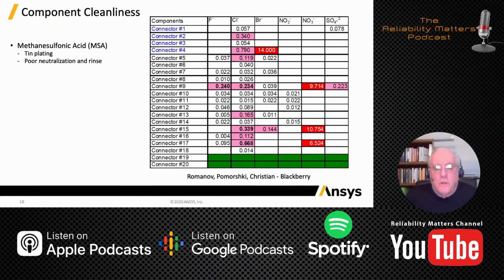So doing a differential scanning calorimetry, they could not find any evidence at all that second step was taking place. So the implication for that is that there is nothing that goes on in that reflow process that makes those residues benign.